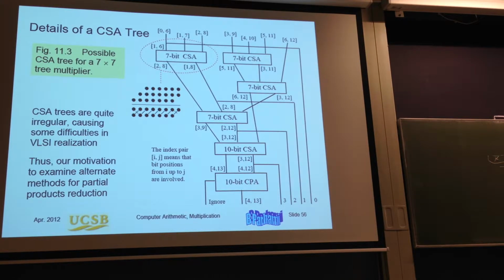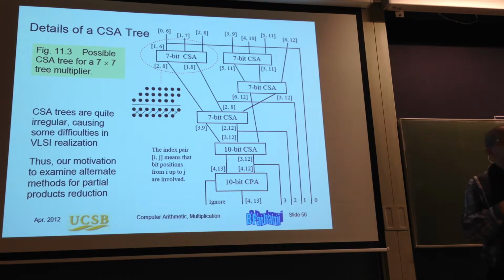It used not to be that important in all technologies, because in all technologies, what was important was the delay per gate. Then the gate was the main contributor for the delay and for the area. Today, gates actually consume not very much time. The most important part is to transfer the information from one place to the other. And even on local wires, if they tend to be too long, this can be a dominated delay.